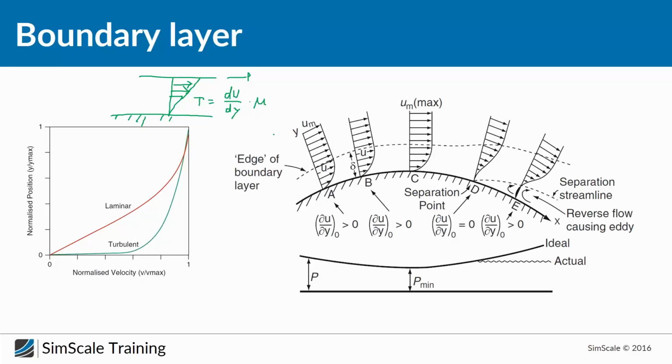And now let's take a look at the boundary layer. Basically it was described for the first time by the very famous German researcher Ludwig Prandtl. And he said that the boundary layer is the area of flow next to the surface where viscosity dominates. And it's limited somehow. If you take a look at, for example, this image where you can see the boundary layer, there we have an edge of the boundary layer. And this edge, in the end, is artificial.